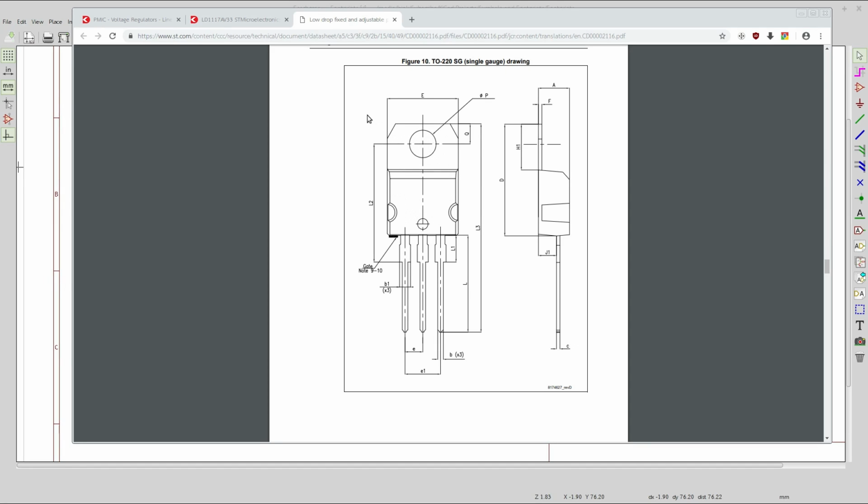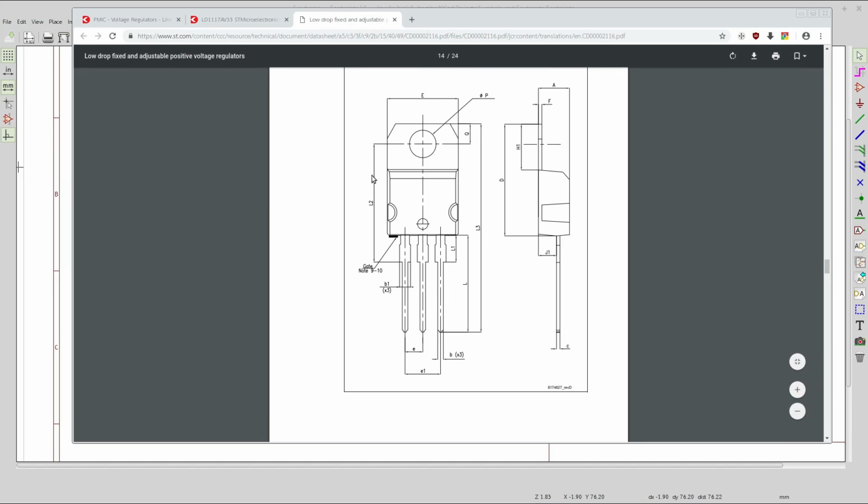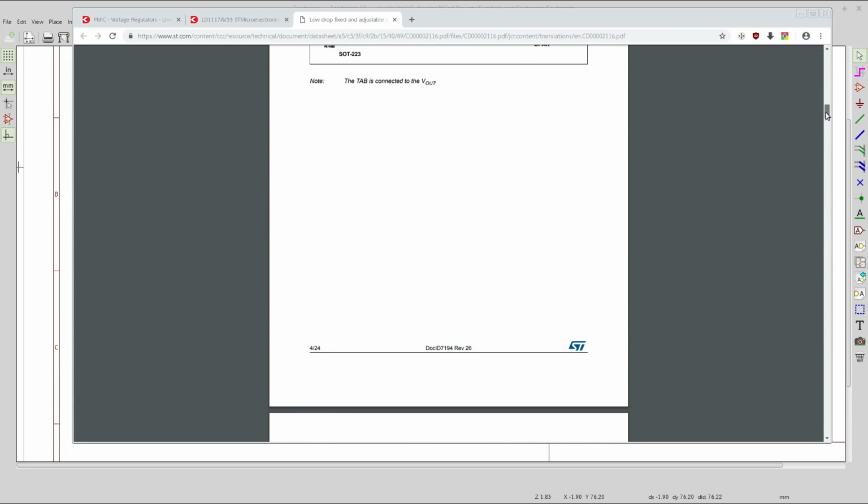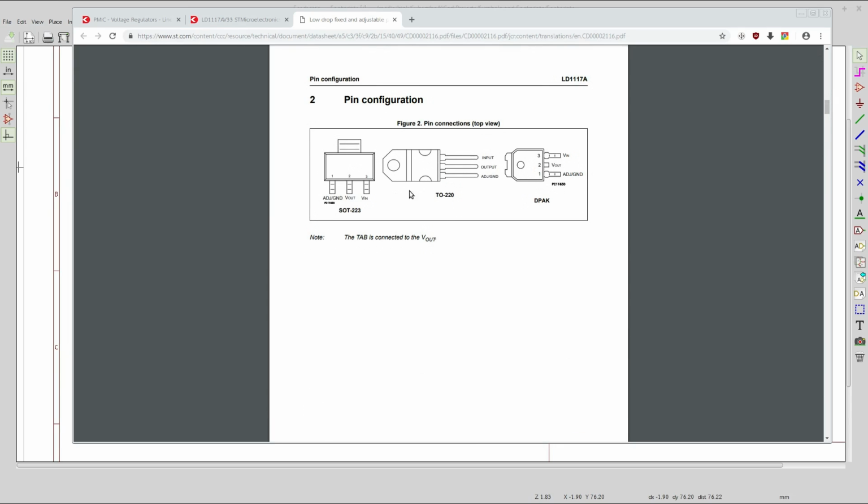Or are you going to leave some copper here that's not grounded in this case, that you could stick it to, to create a little bit of a heat sink? And will you be sticking it down with some thermal adhesive? All that is maybe not super relevant, but if you are laying it down on the board, then in your footprint for the PCB you'll want to create a little square that denotes that that's what's going to happen, so you don't accidentally put other components in its place. You see? So again, for starters, we'll go with this.